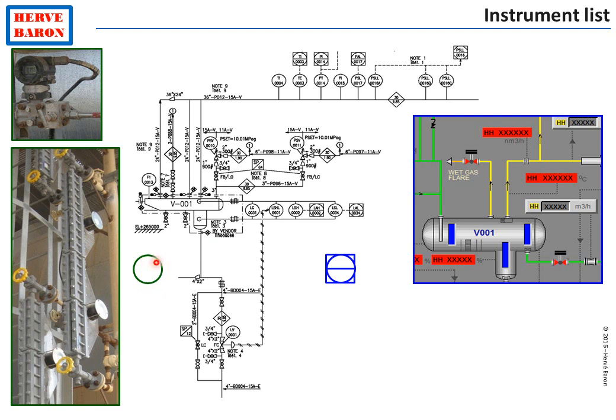This symbology is international. It is the International Society of Automation, ISA, symbology. So, instruments with a circle, local instruments. Instruments with a square frame, available on the operator display remotely in the control room.